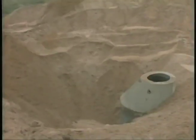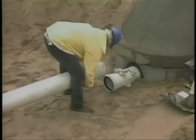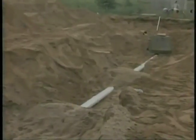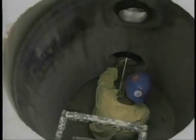To prevent this, manholes are always installed where a change of direction or grade is needed. They are installed 200 to 400 feet apart to allow easy access for cleaning, maintenance, and inspection.